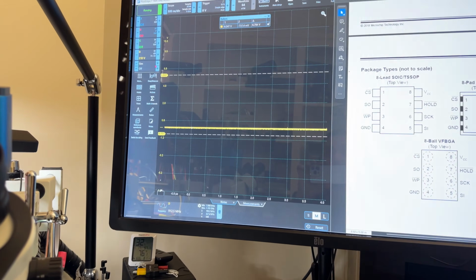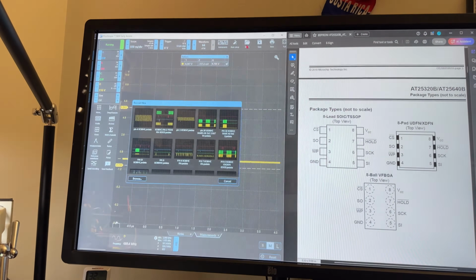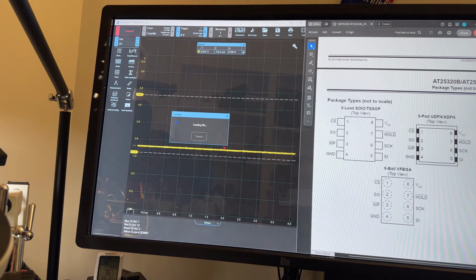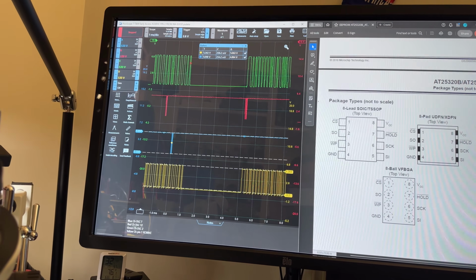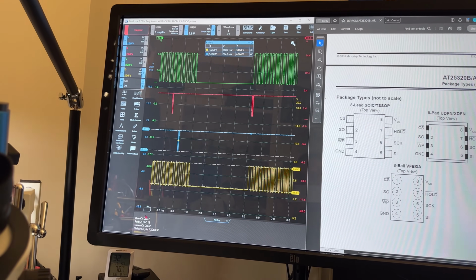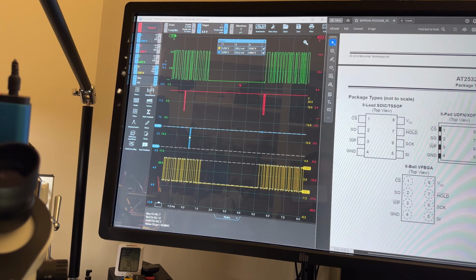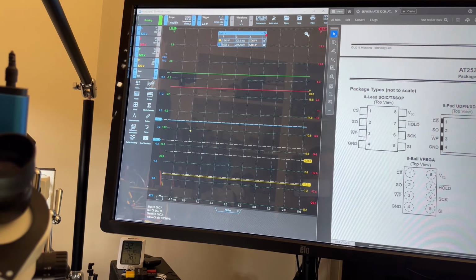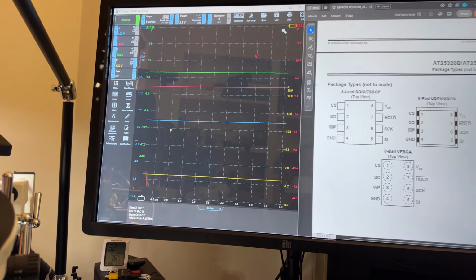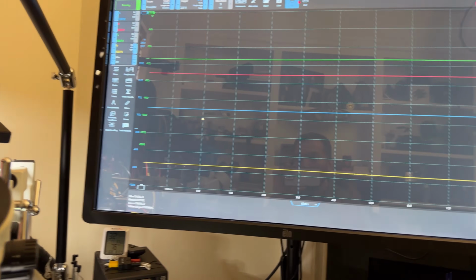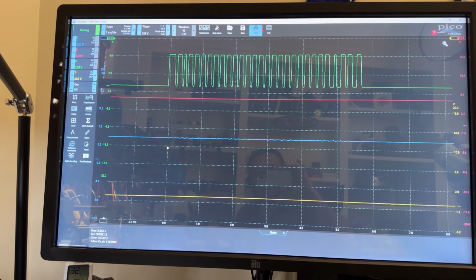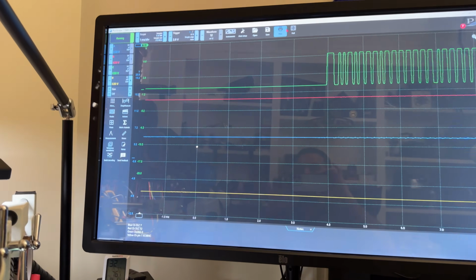So let me go back to the setup where we can see the actual communication. Let me open a folder where everything is, you see DLC 7, 12, and 2 talking. All right, let me run this. Let me take this cursor off the screen so we don't need that. I'm going to make this big for this capture. All I'm going to do is turn this on, and I want you to see the red channel. See the red channel? That's pin 2 in the DLC.